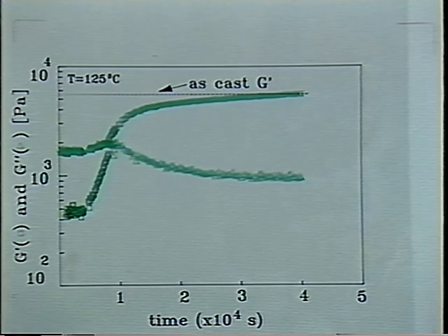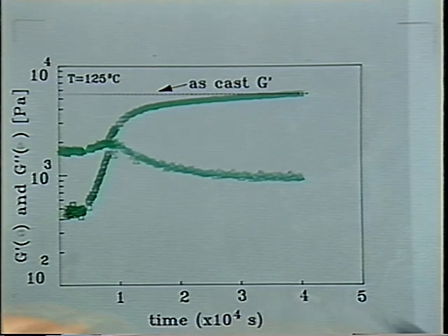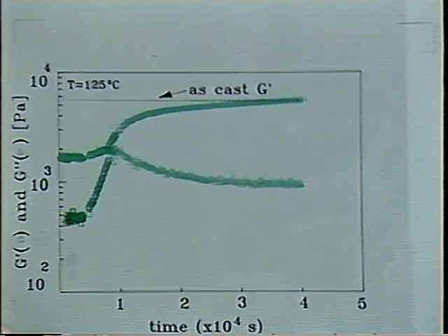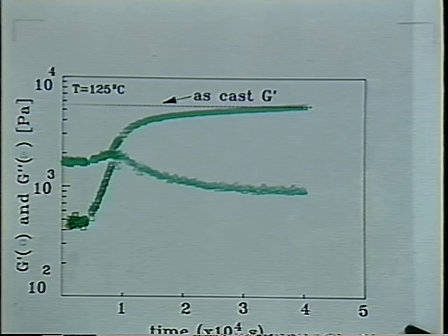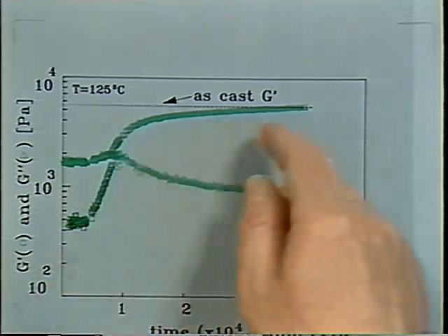In contrast to that, and I don't have the figure here, it's interesting to look at Hashimoto's result. He finds that the sample phase separates very quickly. When he quenches to 125 degrees, in a few seconds he has a fully phase separated structure. Somehow the structure phase separates into cylinders, cylindrical domains, but those cylinders are not connected to each other. They are individual units. And the connection, the healing of those cylinders needs a long time, and as those heal, the modulus is building up.